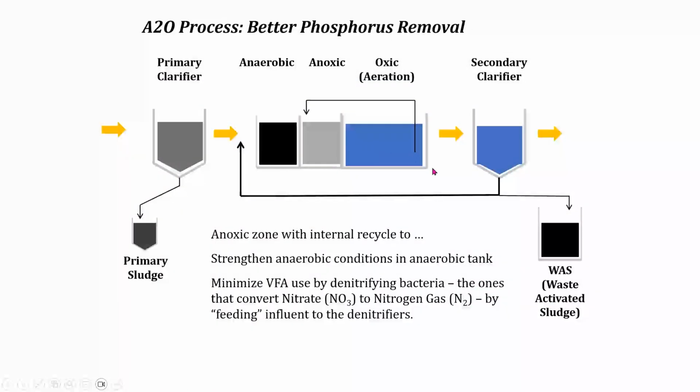Okay, let me go back to that picture and I'll see what we have here for comments. How do you determine the point to test for 3-to-1? Like I said, I'm going to actually show some profiles, but usually your return is somehow going into this flow stream, so you can just grab a sample of this flow that includes the return, and you want the soluble phosphorus on that, so you do not cook your sample.